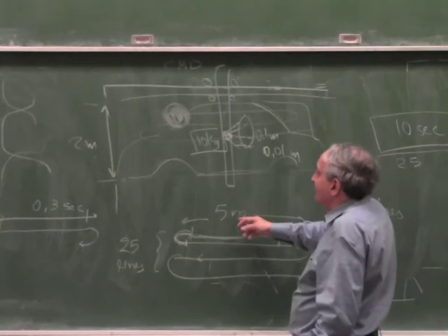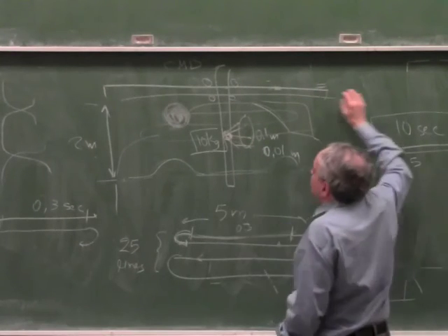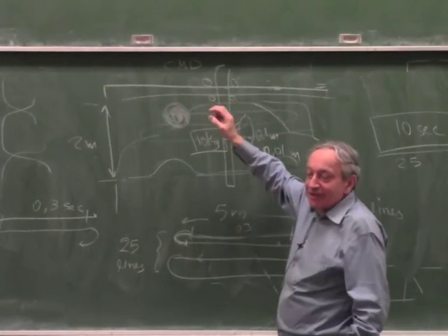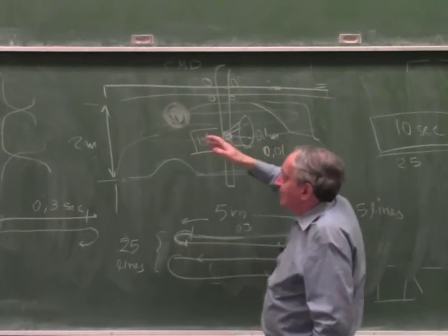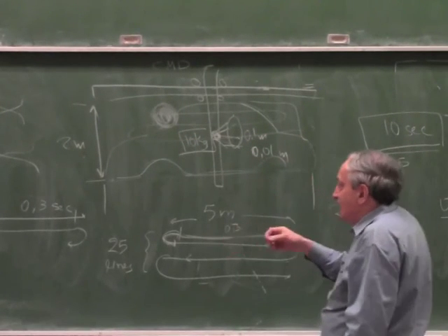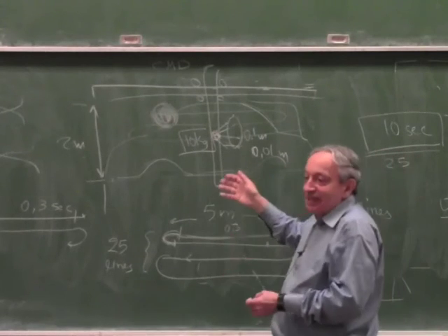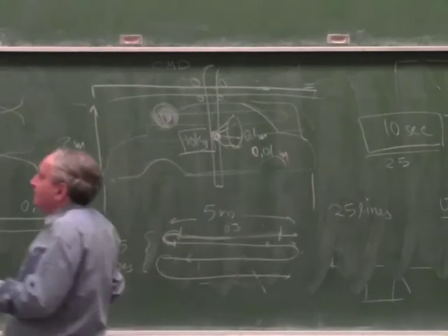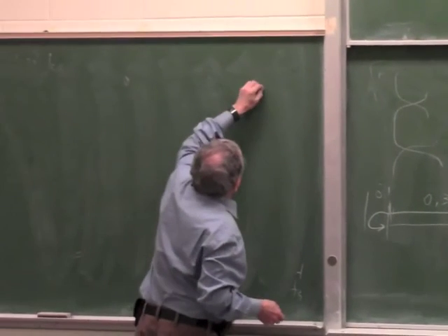Since this is 5 meters, it's not reasonable to do a linear actuator 5 meters long, right? It's more reasonable to put a belt. And that gets into the other part of the question. In these questions, I always say suggest a mechanical configuration, which means you have to make a sketch. How would you actually build it? So you have to think a little bit as a mechanical engineer, saying how would you build it.